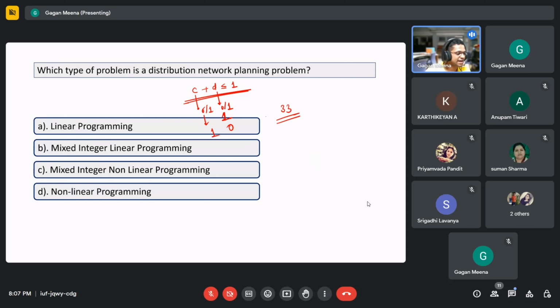And we want to site energy storage. So we have 33 possible locations available. At each location, energy storage can be present or not present. It can be sited or not sited. So that is a decision variable for me, whether it is present or not on that bus. It will be determined by the optimization problem.